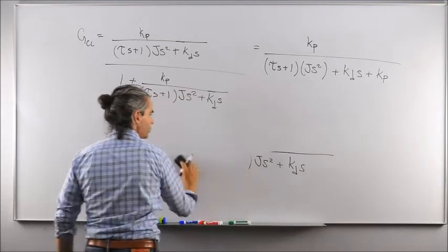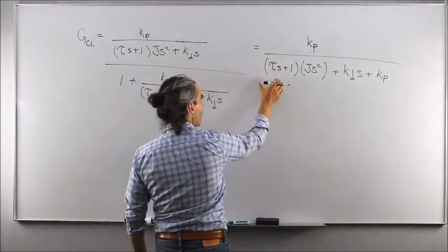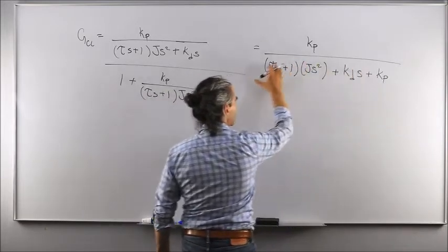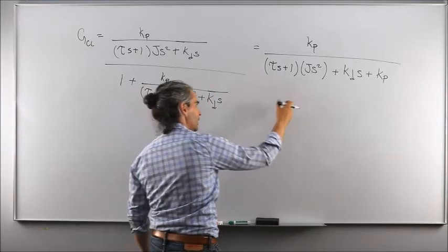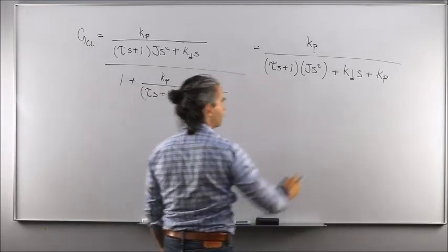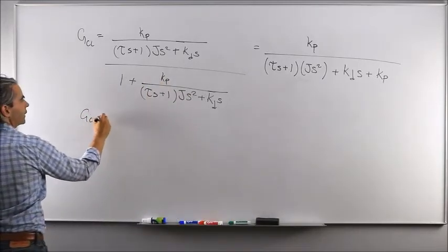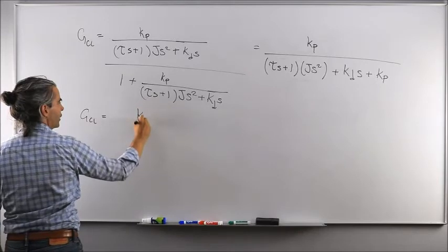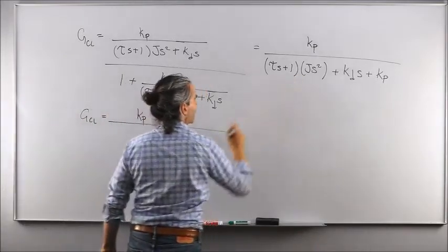And because I know I want to use that within the Routh stability criteria, I know what kind of format I want for my characteristic equation, right? I want, in that case, my s cubed, s squared, s to the power 1, and s to the power 0 at the very end. So therefore, I'm just going to write the closed loop transfer function by multiplying these two terms together to begin with.